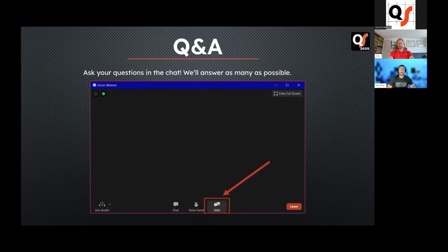But basically what you can do is take a look in QuickSurface Lite, or if you are using Fusion, you can extract those curves from the mesh. So in the longer form version on the YouTube channel, we do talk a little bit about pulling those curves out in Fusion as well. Depending on which one you're using, you can see that. But I would always say go back to manual measurements for critical features and then rely on the mesh as a reference.